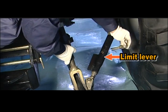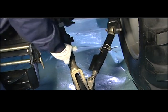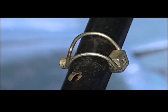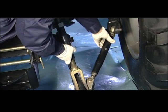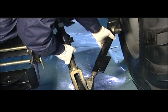Limit lever. The limit lever mainly restricts the lateral swing distance of the tool. Insert the lock pin into the lateral hole of limit socket so that limit lever is fixed. Insert the lock pin into the mid hole of limit lever. The lever will have certain movement allowance.